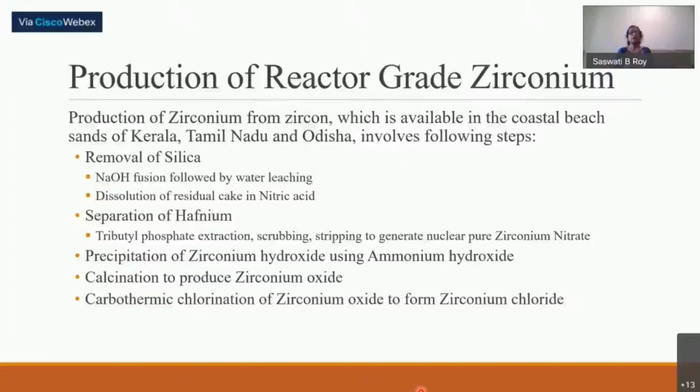And for this hafnium separation, the equipment used is a slurry extractor. The size is very big, as they form quite stable emulsion during settling. So the big settlers are good for this, and slurry extractors are being operated very efficiently for several tons of zirconium processing. So after extraction, what happens in the extraction?